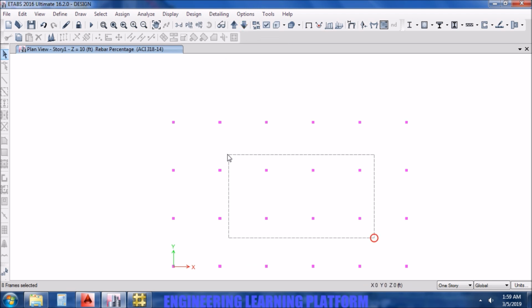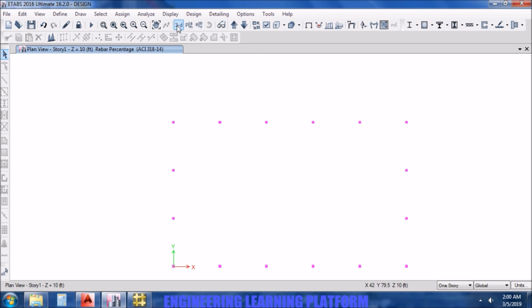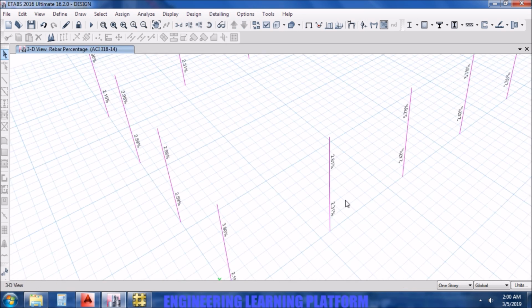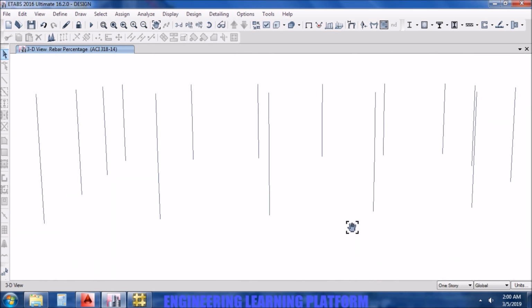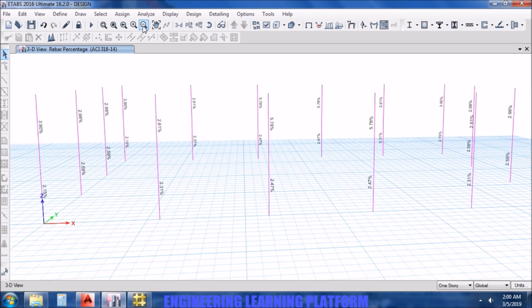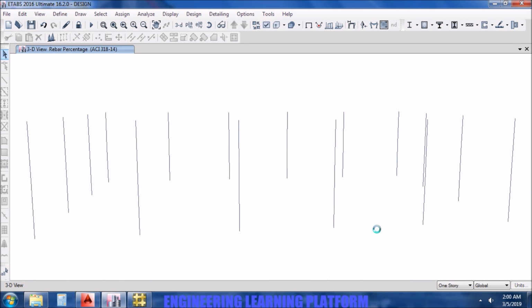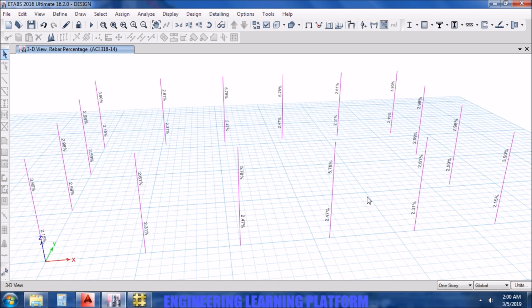But logically we won't place the steel as shown. We will place the higher steel in any story in the bottom first. That is also good to know from stability point of view. Since the higher percentage of the column is coming in the higher stories or the top story, we need to check thoroughly in all of the columns to get an idea what we will be incorporating in the design.